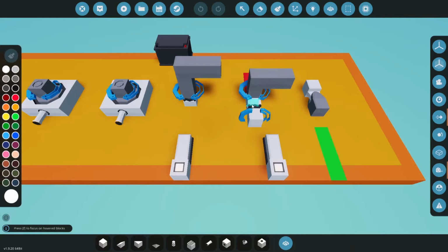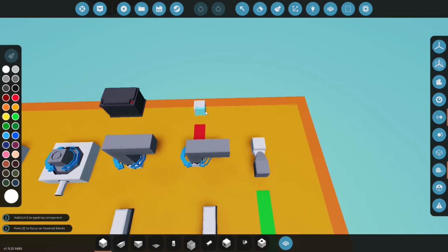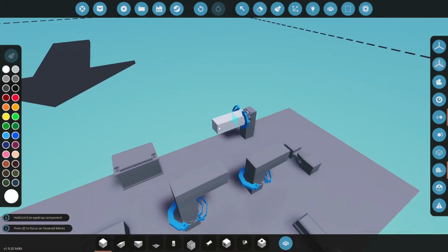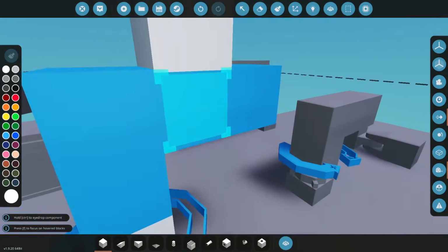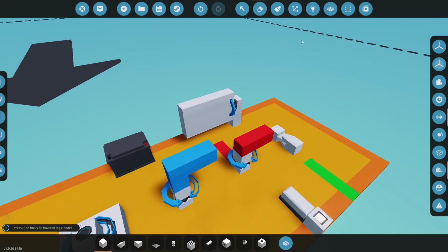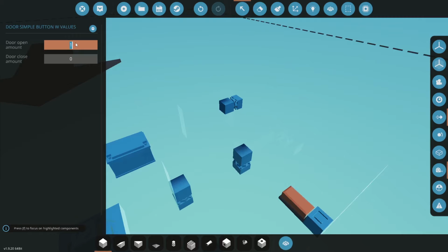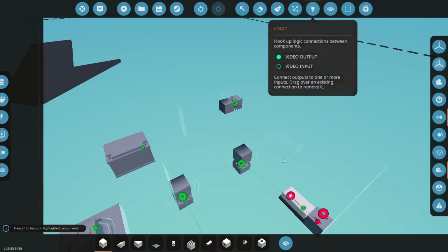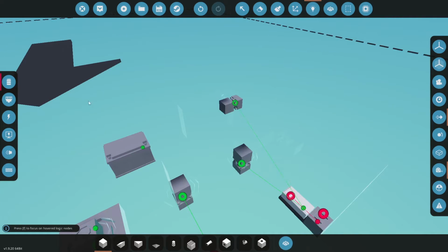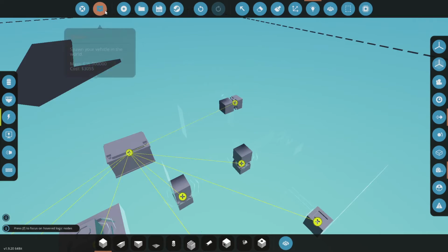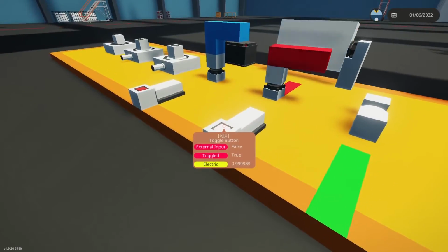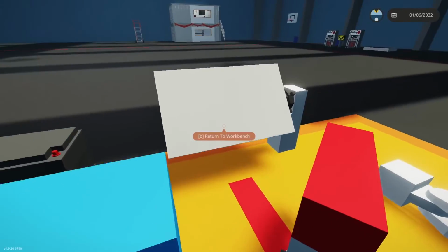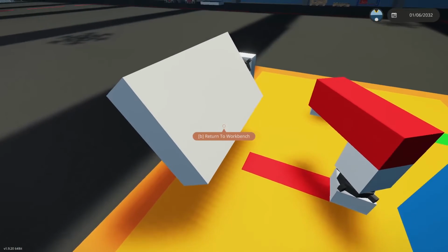This is how you'd, for example, put an instrument panel at an angle, and all you do is put your pivot as such, and then put your instrument panel or whatever like this, and then you want it to be, say, at a value of, let's go 0.4. Let's not go, because we don't want to make it flat. That's not the intention. We want to make it at an angle. So if we spawn this in and press the button, you're just going to see this is going to go to 0.4. So that's a nice slanted instrument panel angle that you have here.